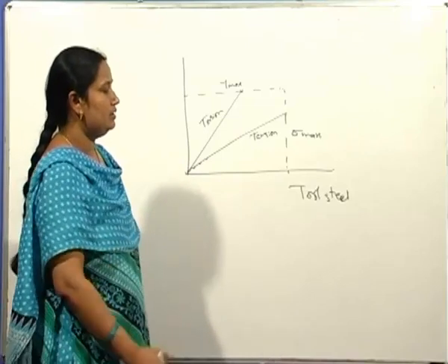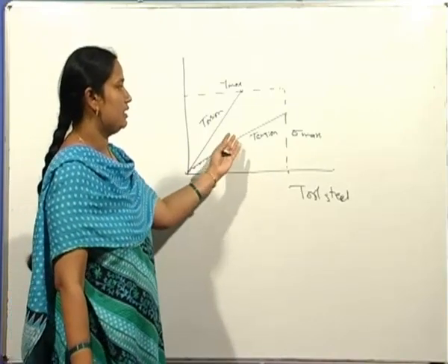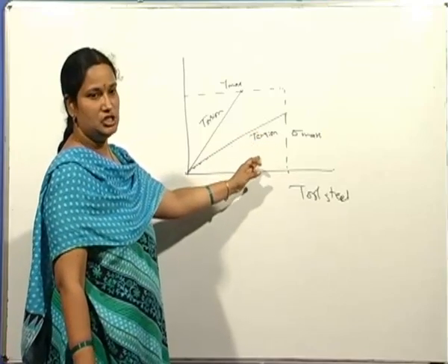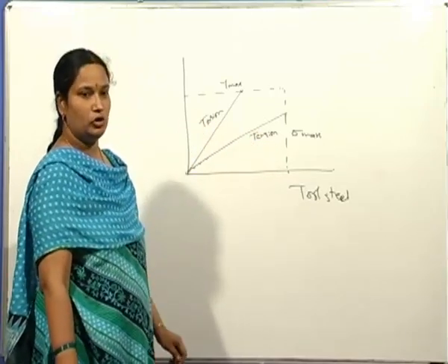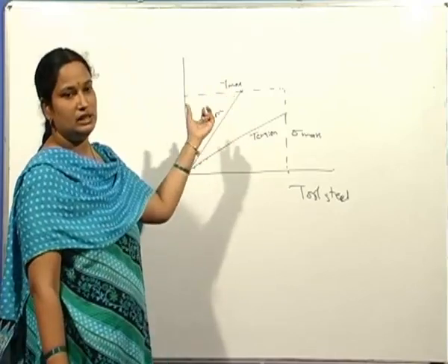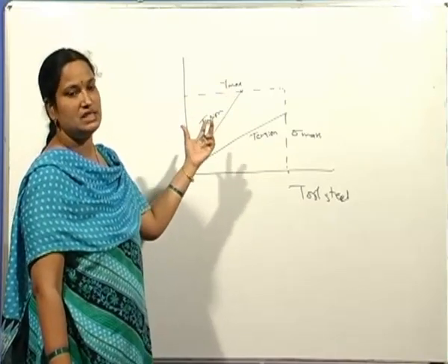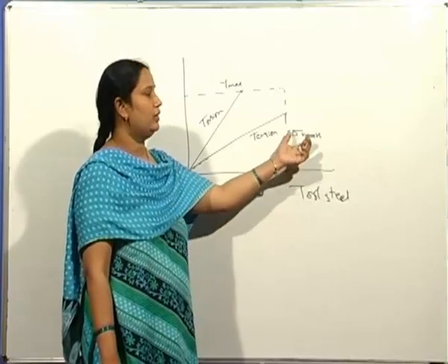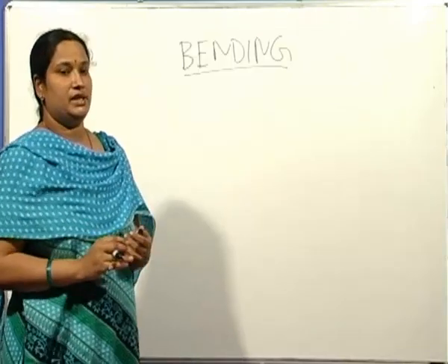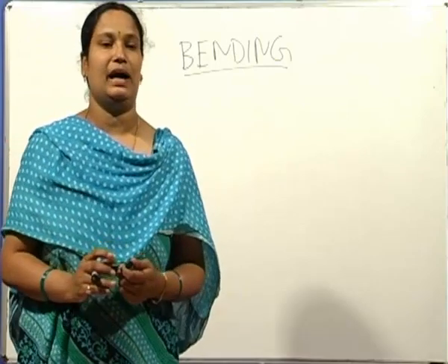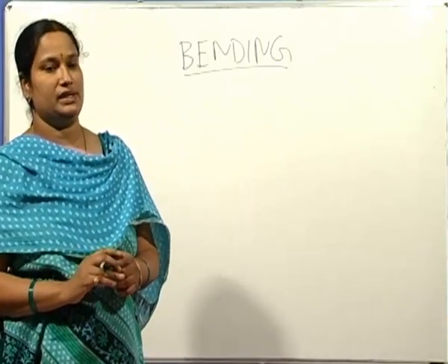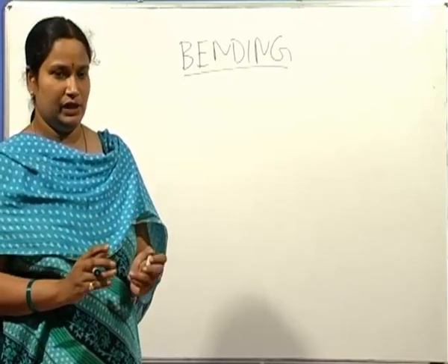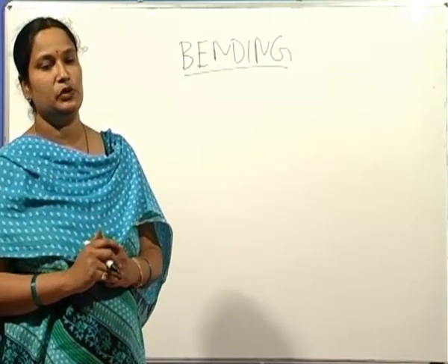A material which fails in a brittle manner in tension, in the case of torsion reaches the critical value of shear stress to cause plastic deformation before reaching the critical value for failure. Brittle materials like ceramics and carbides cannot normally be tested under tension because it is very difficult to prepare the specimen to dimensions.